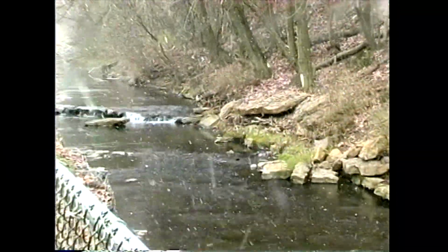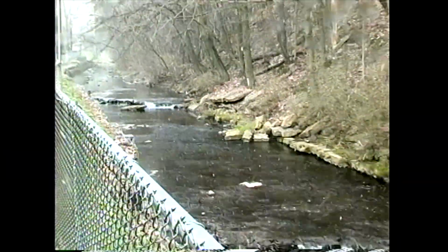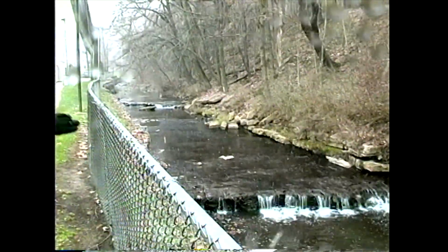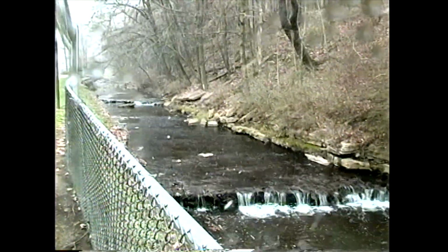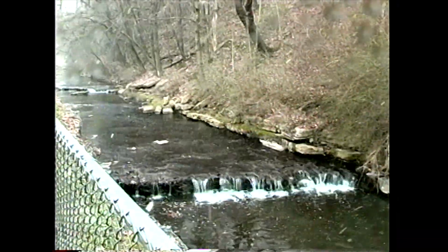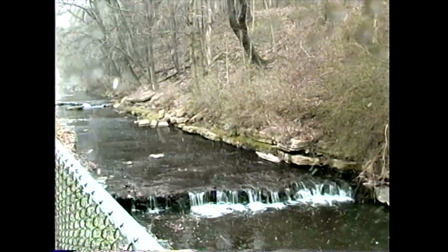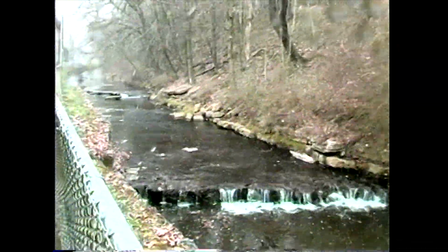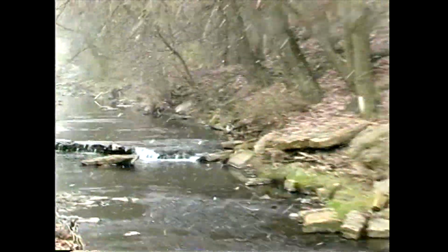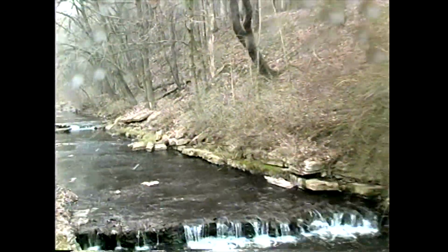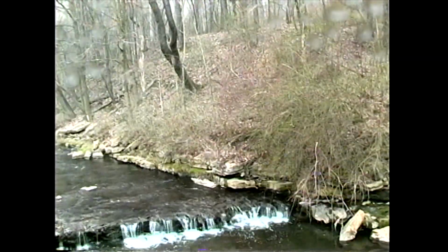See the stream entrenching very well. McLaughlin Run never was straight like this. Years ago, 30, 40 years ago, whenever it was, McLaughlin Run was pushed over to this point, and if you look down the stream, it has no flood-prone area, no floodplain. But you can see bankfull, and bankfull is basically this first lip you have right here, coming up where the grass starts to plane out. That's about where bankfull is.